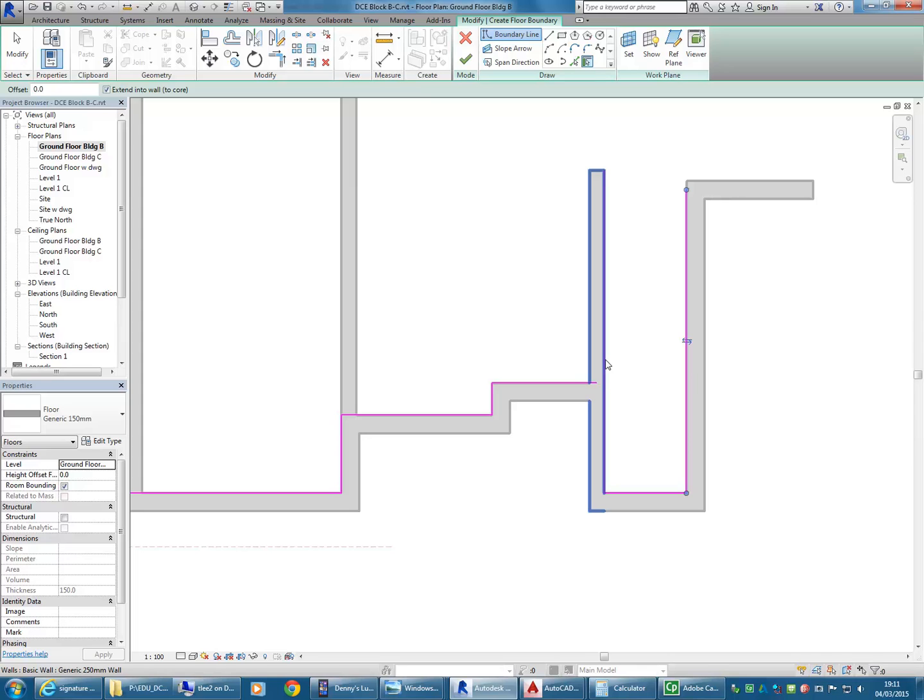So in a brick building, they typically have the floor supported on the brickwork. You have two skins of brickwork, and the inside skin is supporting the floor. So the floor is basically sitting right on top of the brickwork of the inside skin, and then they build new bricks on top of the floor again for where it continues above that floor. So you can't really count the number of bricks going up from the inside, because we'll get a little bit off because there are floors there. Yeah, exactly. We can't see the bricks here, but that's right. So that's the way it is in reality.